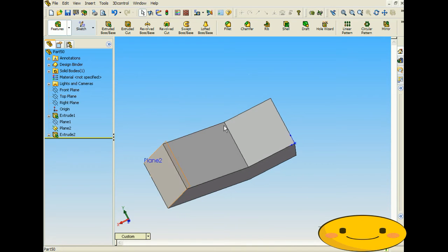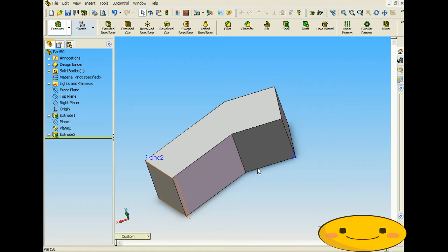So you can use this when you're in a sketch such as this, if you're in a part and there are different planes that you're working off of, you're able to extract and pull from other parts and planes. So using convert entities, it's just like you're at a view, and then you can pull all those lines onto your view, and then you can play with it.